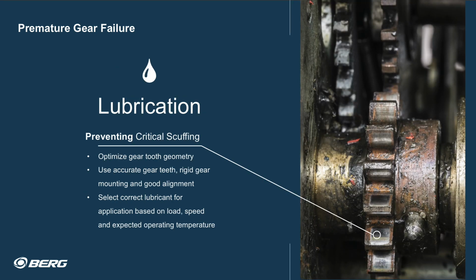Much like for temperature, improper alignment can have significant negative effects on the performance of lubrication in the gearbox. Misalignment can cause the contact area to exceed the maximum force the hydrodynamic lubrication layer can support. This can result in direct metal-to-metal contact and, as you would expect, significantly accelerated wear.